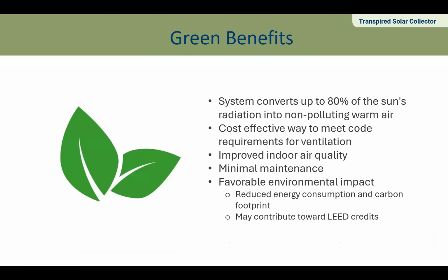So green benefits to the system: converts up to 80% of the sun's radiation into non-polluting warm air, cost-effective way to meet code requirements for ventilation. So if you have a high air exchange requirement space, say a lab or something like that, in the winter months, last thing you want to be doing is bringing in 30 air exchanges in a cold weather climate per hour, when you could have this system bringing it in at a higher temperature.